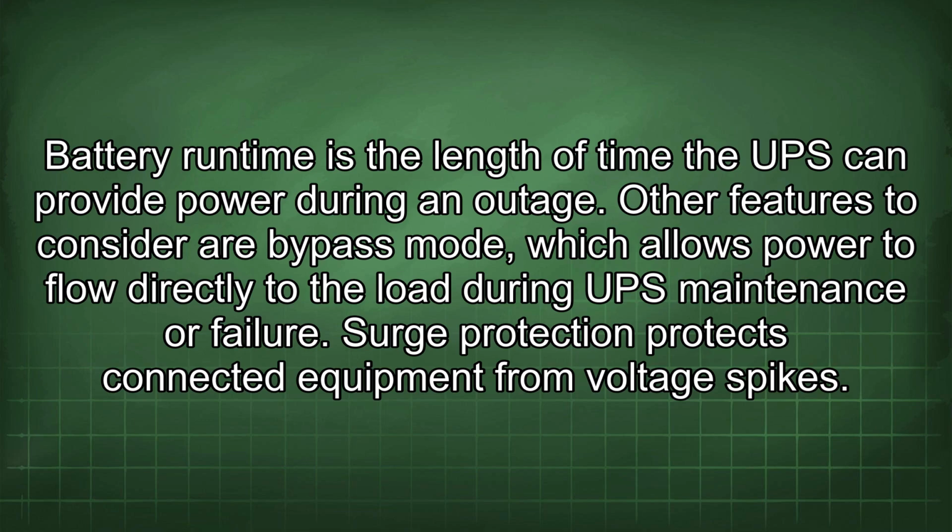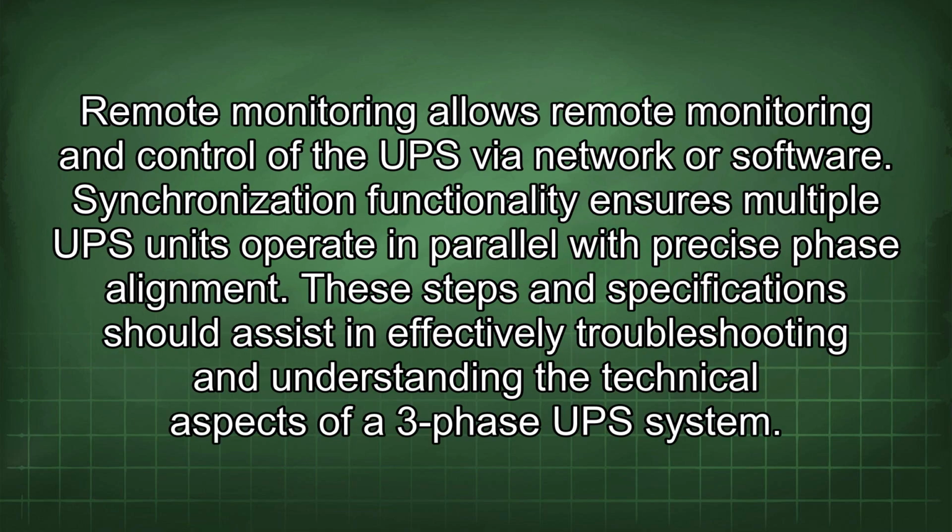Other features to consider are bypass mode, which allows power to flow directly to the load during UPS maintenance or failure. Surge protection protects connected equipment from voltage spikes. Remote monitoring allows remote monitoring and control of the UPS via network or software. Synchronization functionality ensures multiple UPS units operate in parallel with precise phase alignment.